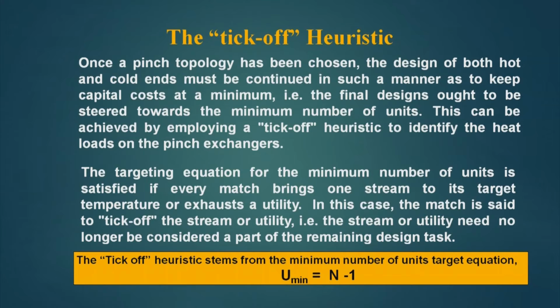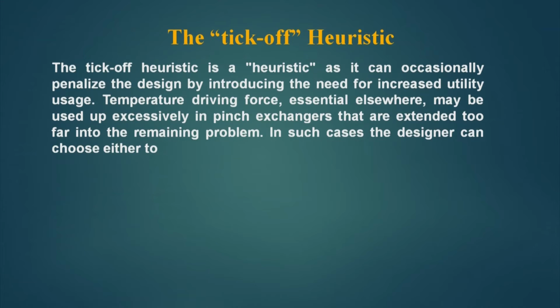The same thing it tells, that when we are exchanging heat, we will try to maximize this exchange, so that a stream is ticked off. In this case, the match is said to have ticked off the stream or utility. The stream or utility need no longer be considered as a part of the remaining design task. The teacup heuristic is a heuristic, as it can occasionally penalize the design by introducing the need for increased utility usage. This has also been seen.